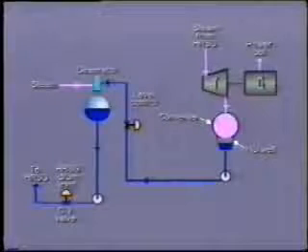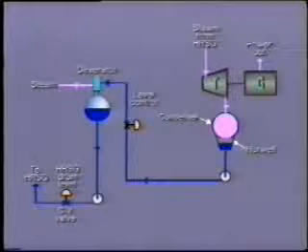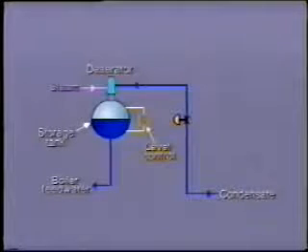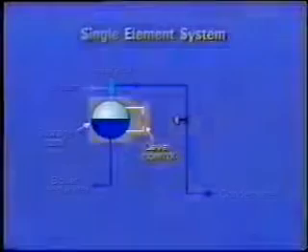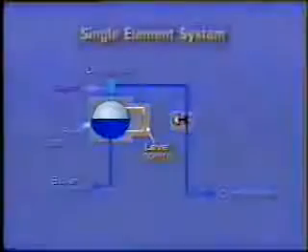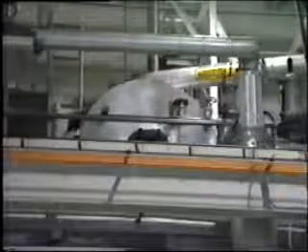In the last segment, we talked about level control in the condensate and feed water system, specifically the hot well and de-aerator. They are both single-element systems. They work on a simple monitoring of the level with consequent signals to the inlet valve. Control of water level in the HRSG drums is more complicated. Each of the pressure sections has its own independent feed water control valve and attendant control system.